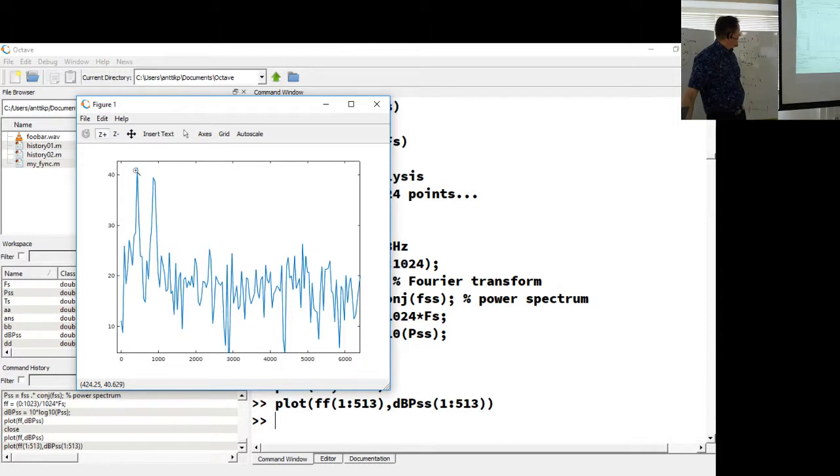So it had a 440 hertz signal, then it has the first harmonic, so it's 881. I don't have enough spectral resolution to say it's exactly that, 882 hertz here. Then we also have this noise here. So noise actually appears as these spurious peaks on the spectrum.